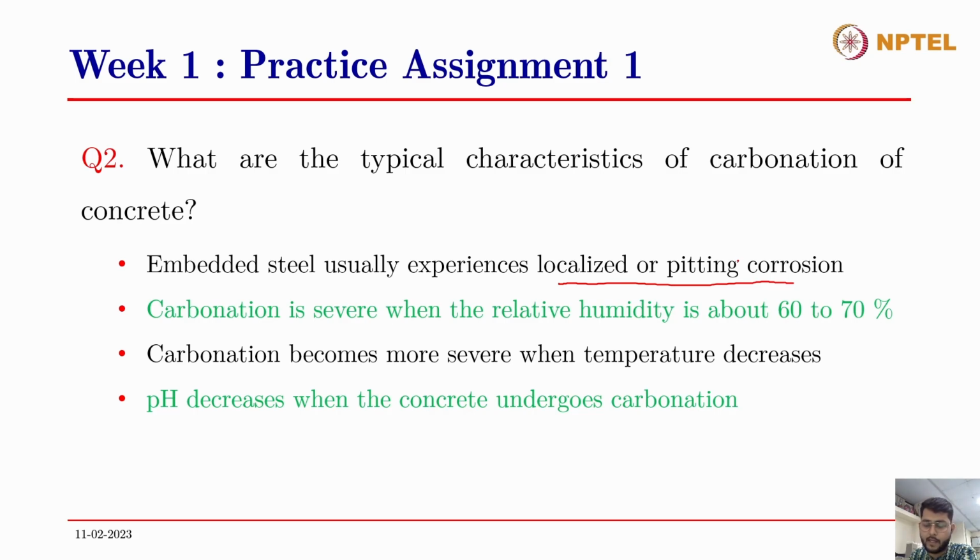So the chlorides, as we have also discussed in the last class, attack a particular region of the reinforcing bar, in which the pit becomes an anode, and the surface of the steel becomes a cathode, and these cathodic and anodic reactions take place, and the corrosion products are formed. And again, HCl is formed, and the pH is reduced, and this gives rise to a vigorous process of pitting corrosion.